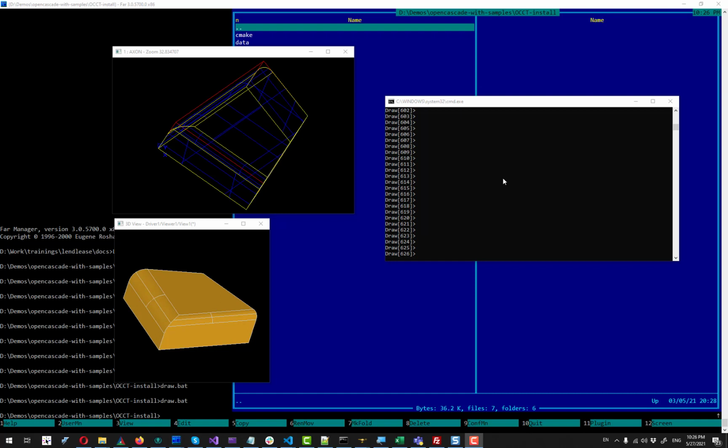Now if I want to communicate my shape to some external CAD package like SolidWorks or CATIA for example, I can export it to some open format like step, and here I'm going to use this step translator of OpenCascade, which is a pretty amazing thing. It's very robust and efficient, so let's benefit from it here, and for that I'm going to do a couple of checks before I go for this export routine.